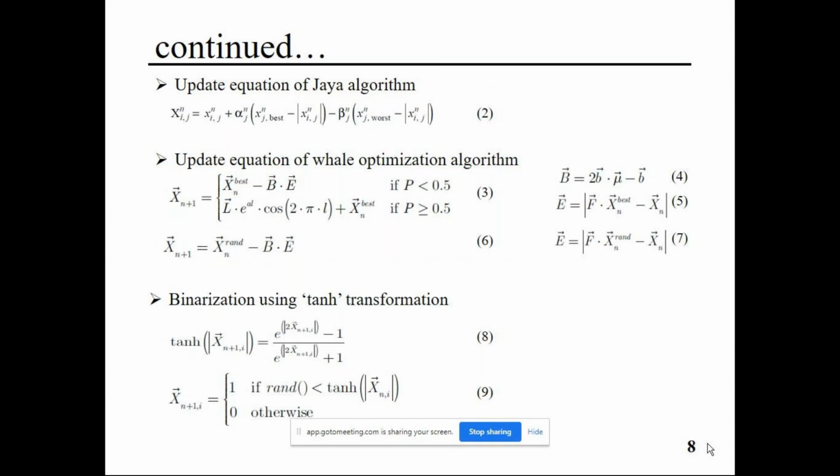But is it really the case? You have to take a lot of factors into consideration. What are the possible factors when you are exchanging the information from the PMU to the PDC, the phasor data concentrator? The communication infrastructure, the congestion in the communication, and the priority of the exchange of information with the routing if a communication failure is there.